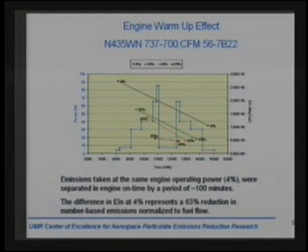We're not sure what's driving that. The engine manufacturers would argue that there is no temperature-dependent component in the engine that's going to have a time constant on the order of 100 minutes. What's more likely to be the case, but it's not resolved, it's still an issue of conjecture, is that in fact what we've got going on here is a time constant associated with the heating of the sampling system.